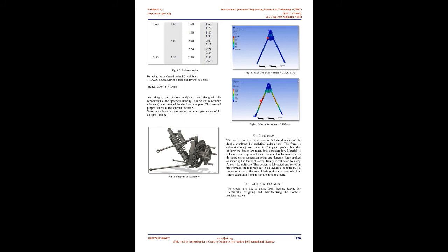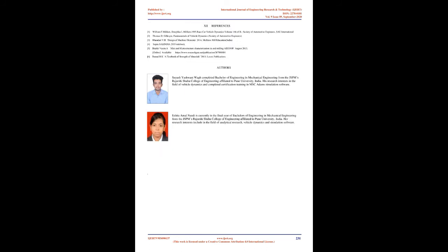The necessary steps in designing a vehicle's suspension are: selection of the suspension type to be employed, selection of the wheels, establish the vehicle's dimensions, wheelbase and track width, model the suspension geometry, designing components. 7. Load transfer. The inertia of a mass is its resistance to change its state. For the change of state of a body, it must experience acceleration in its motion direction. Acceleration, braking, or cornering is nothing but the change of state of the vehicle, which offers resistance for a while and results in load transfer in a direction opposite to the force causing the change. No doubt, this load transfer persists for a short duration of time, but its impact on the car's performance is much more crucial.